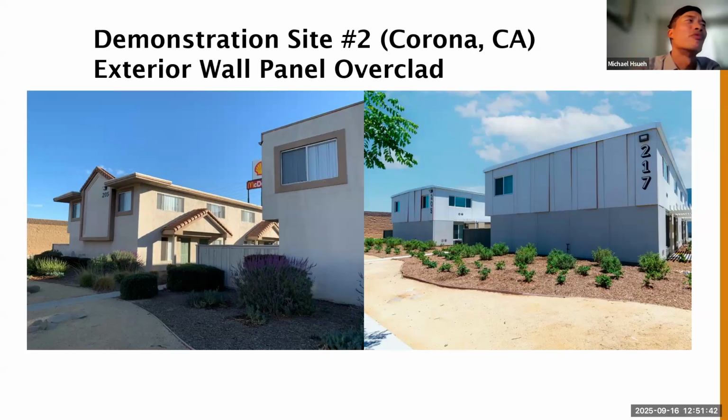I have some photos, maybe not in the slideshow, of the installation of those, such as measuring the moisture content within studs. I don't have graphs of that data, but we also installed moisture and temperature sensors inside the walls at Corona, where we had the wall retrofit. I don't have that data fully put together right now, but that is an ongoing data collection process.